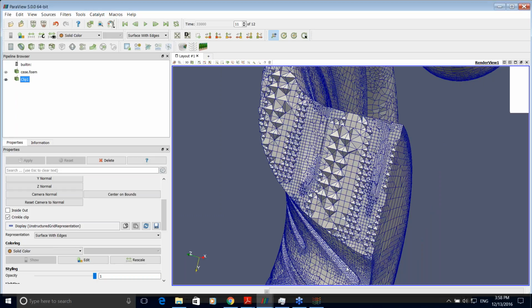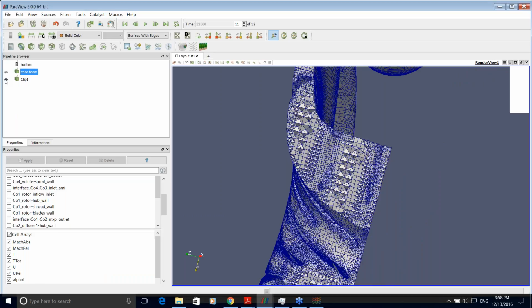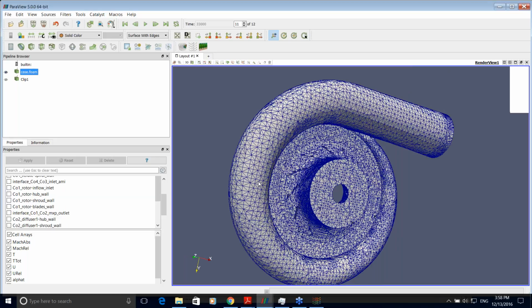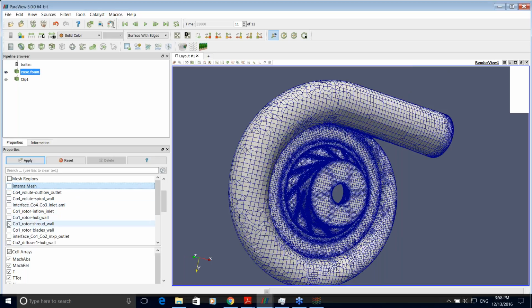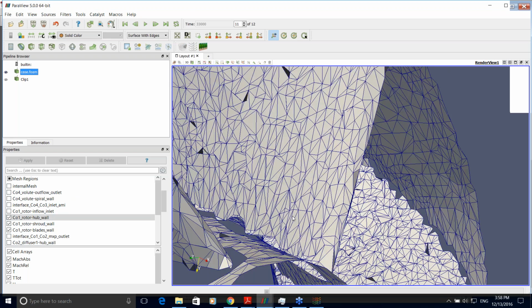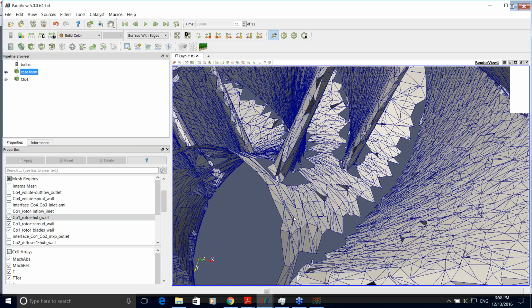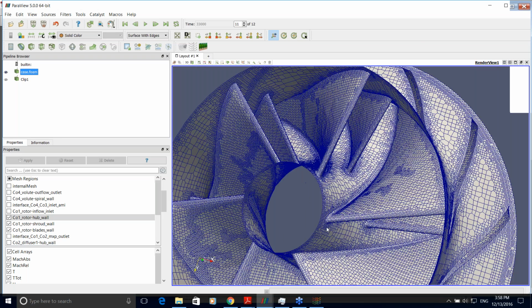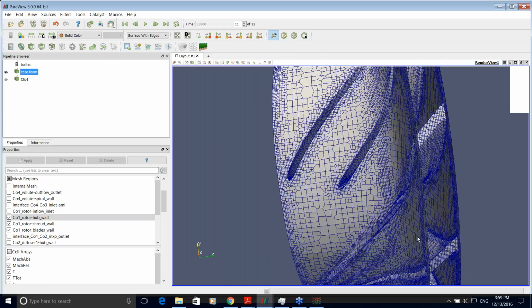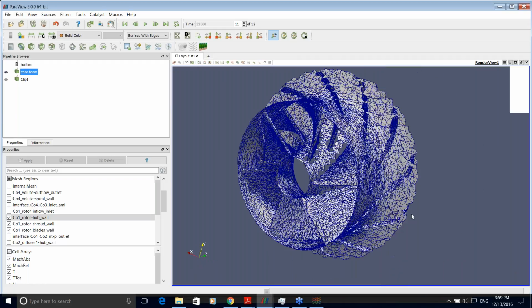It's highly automated, a great tool for very complex geometries, and it's very robust in terms of which machine you do the mesh on, and the results are the same. It's also a hexahedral dominant mesh, like 90% of cells are hexahedrals. So we have really great experiences with SnappyHexMesh. Yeah, that's from me.